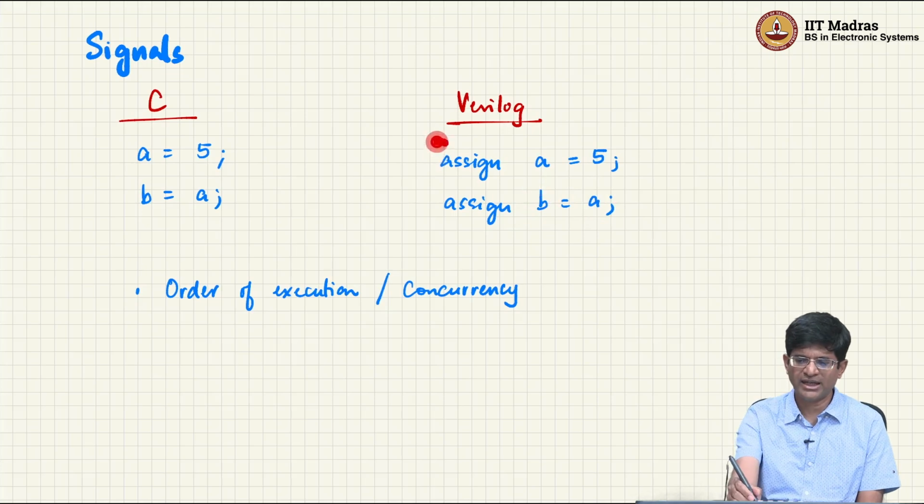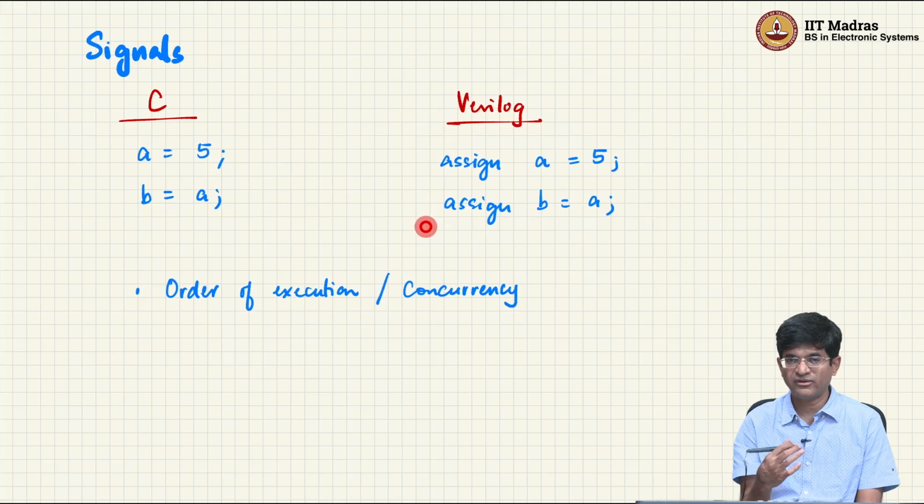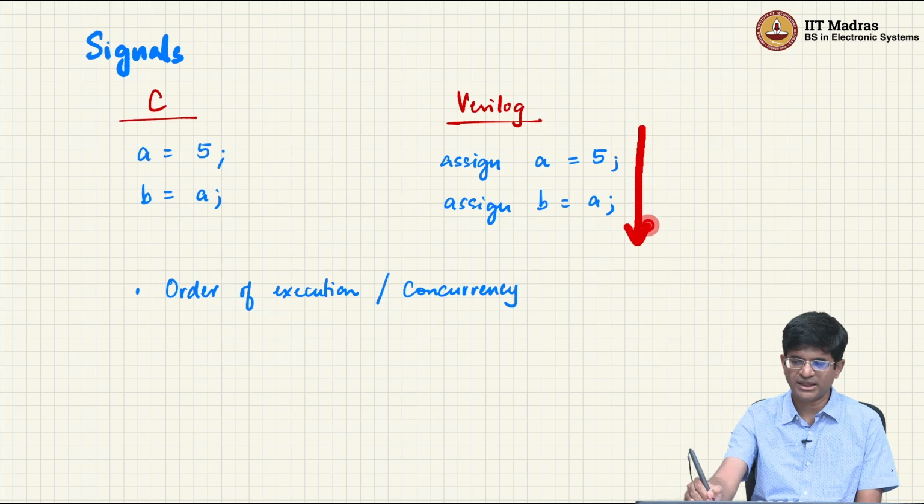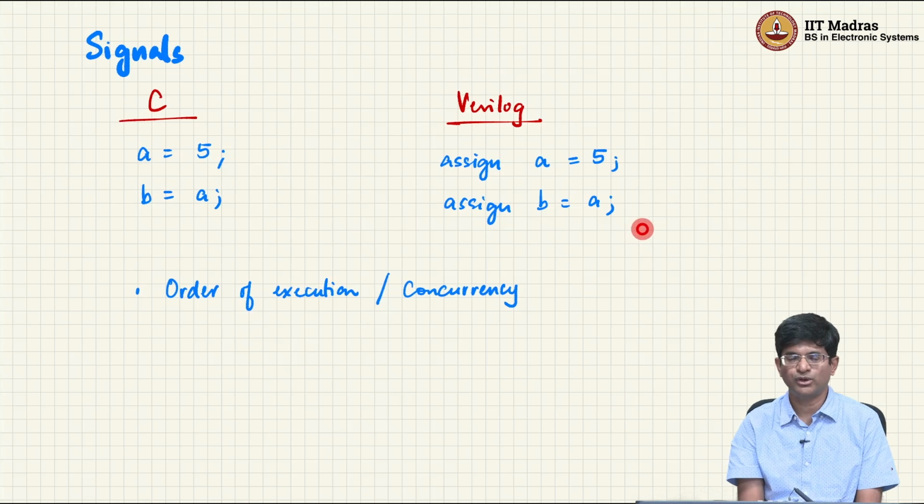So, eventually I might end up with the same kind of behavior as what I saw on the left hand side, but the way this gets evaluated in a Verilog simulation is actually quite different and is something to keep in mind. The order of execution in Verilog is not specified, right, and if you depend on something happening in a specific order for your simulation to work, it is likely to get you into trouble when you actually synthesize something and build a final circuit.